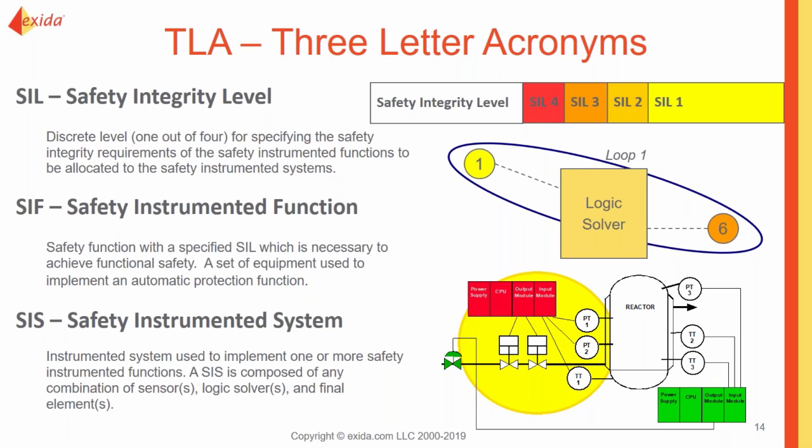Next, we have a SIF, which is a safety instrumented function. And a safety instrumented function, if you think, is kind of simplified, it's going to be one set of actions corresponding equipment needs to go with one single hazard to bring it to a safe state.